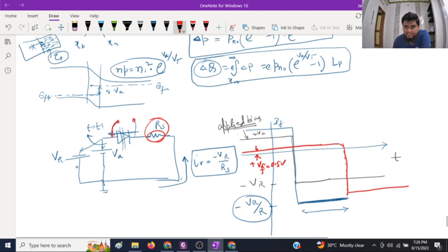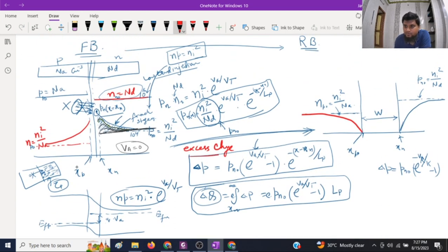After that, what will happen is that, because we have to come to this stage, once all the charges have been recombined, but still to come to a reverse bias of plus on this side minus on this side up to approximately VR, what will happen? These charges will actually start depleting from the junction.